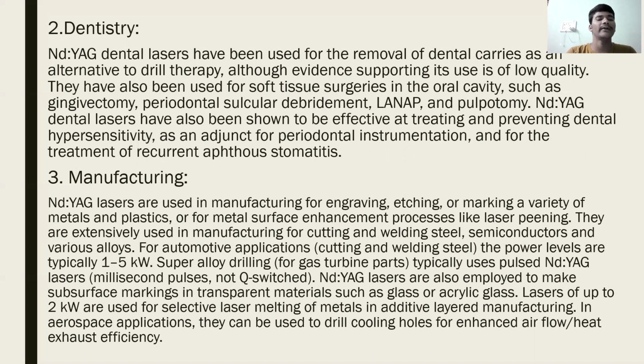Not only for biological purposes, it can be used for industrial purposes also, like manufacturing. Nd:YAG lasers are used in manufacturing for engraving, etching, or marking a variety of metals and plastics, or for metal surface enhancement processes like laser peening. They are extensively used for cutting and welding steel, semiconductors, and various alloys.